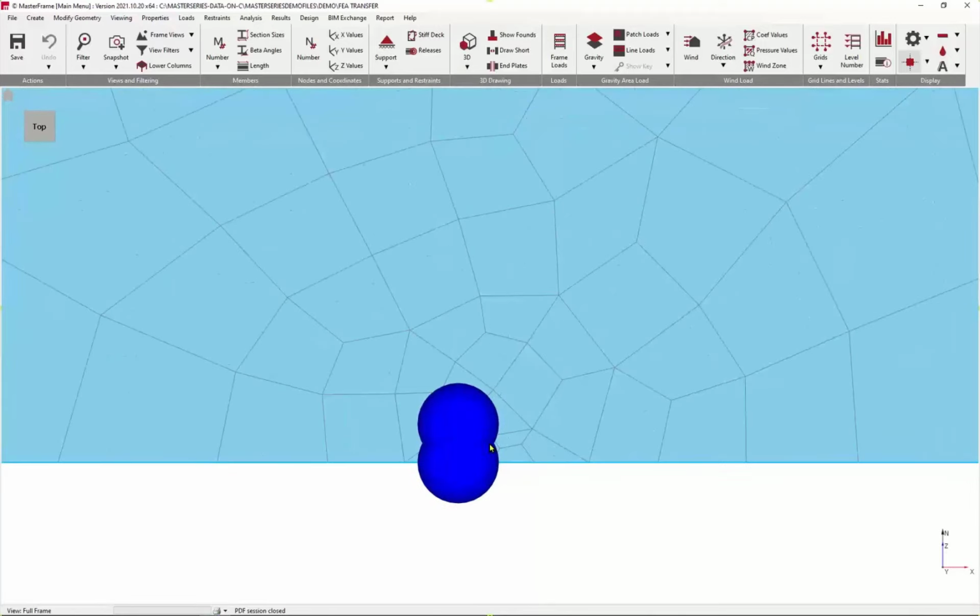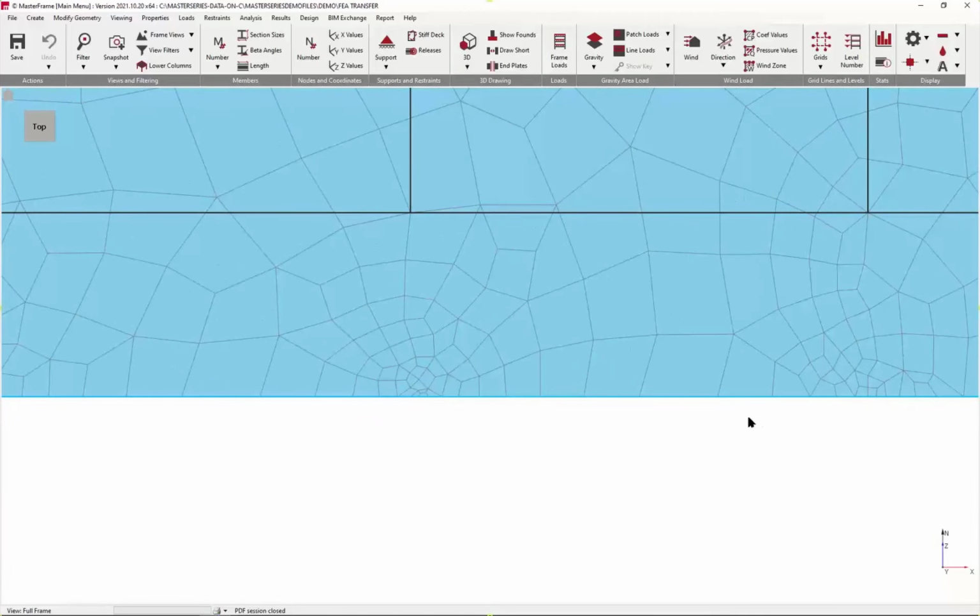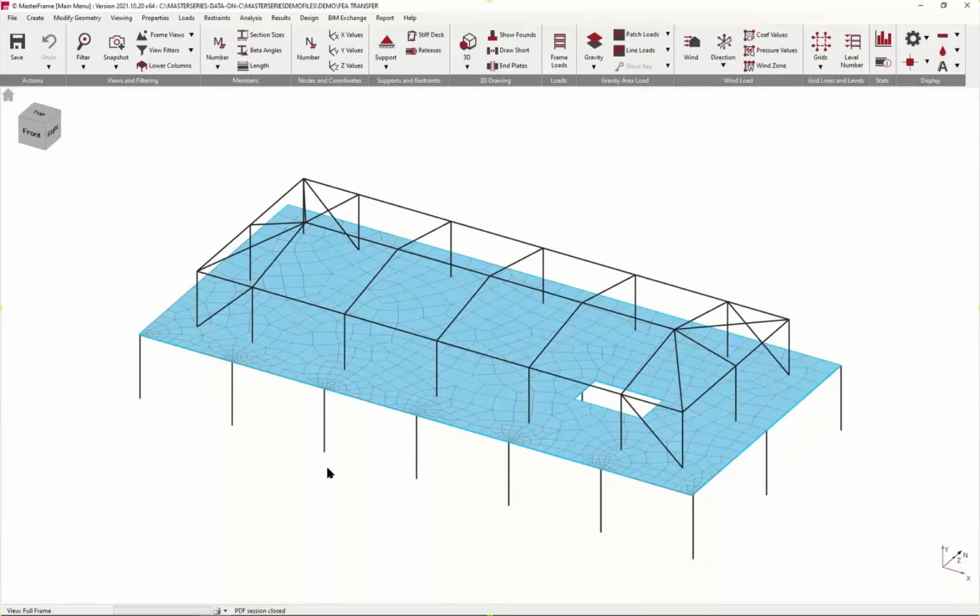And you'll see that we can end up with quite obtuse shapes. They're still quadrilaterals and they're still valid, but occasionally with these very close distances together, you can get surface elements that are nearly triangular, which will cause you errors and the like. So we don't recommend that you pull these in unless you have to. So if I just took those all back out again, no, I'll leave them as they are because it'll actually